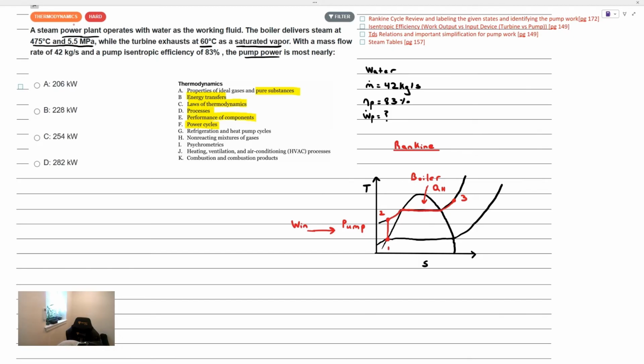The next thing that we're going to enter into at state point 3, which is the exit of the boiler, is the turbine here. The turbine produces work out, and that occurs via expansion. You can see that all these lines, the work input and output that I'm drawing, are isentropic, constant entropy. That's why they're fully vertical here. And we return back to state point 1. This device here is a condenser, going from a saturated vapor at state point 4 all the way down to a saturated liquid.